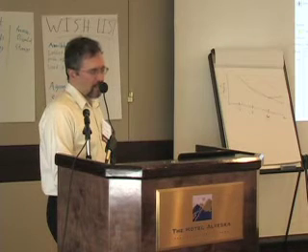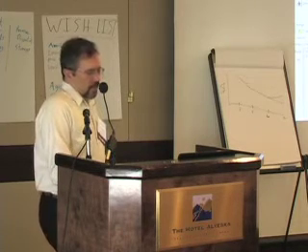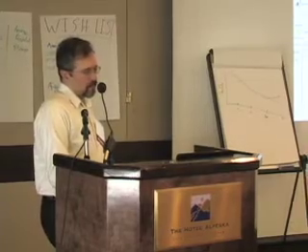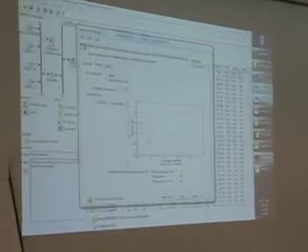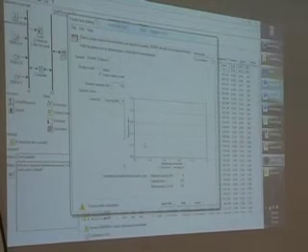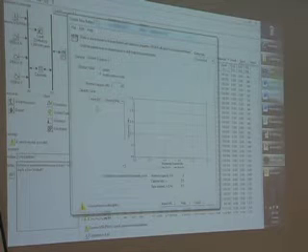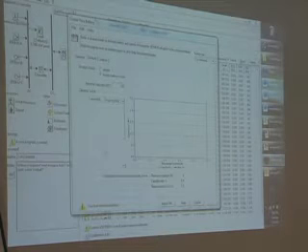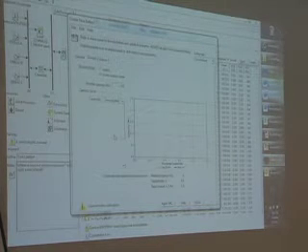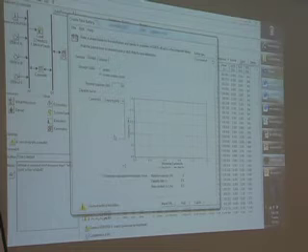So if you're working with a conventional battery, traditionally we had this kinetic battery model where you put in the amp hour capacity of the battery as a function of the discharge rate. This is standard data that you can get from the battery manufacturers, and it varies quite a bit.